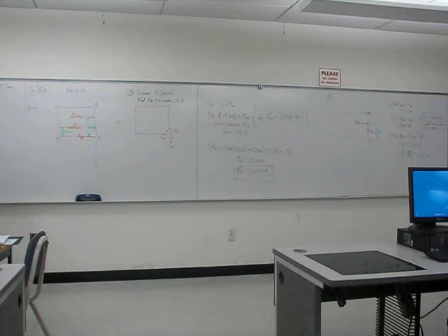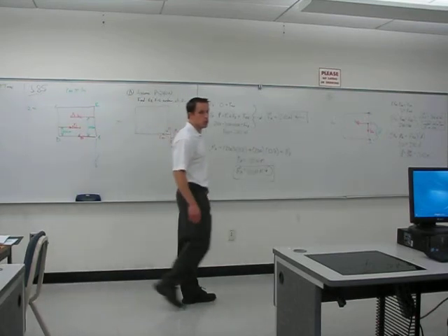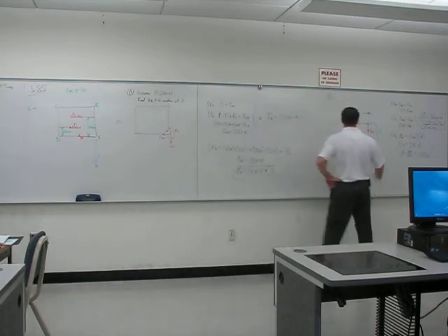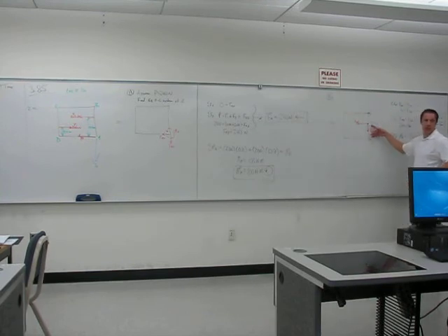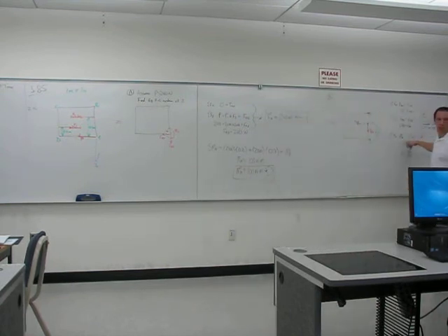Sir, on the second question, it said we all are applying force at point A, right? Right. But the force P has some effect on that particular moment, right? On question B, because we got a perpendicular distance and then we got a force going in the Z direction. You're looking at this picture. We got a force P, 240 newtons, going in the Z direction. So you're saying the force P should have shown up in this equation over here?